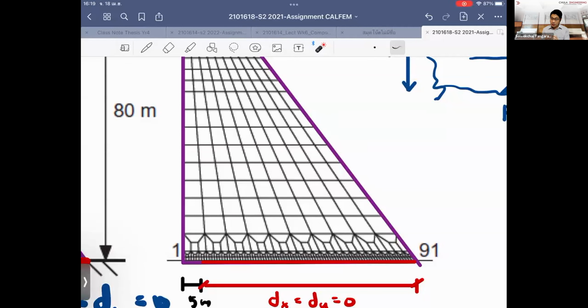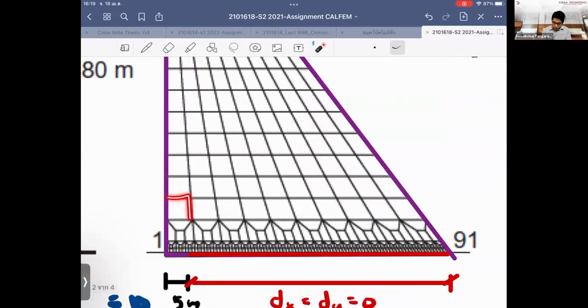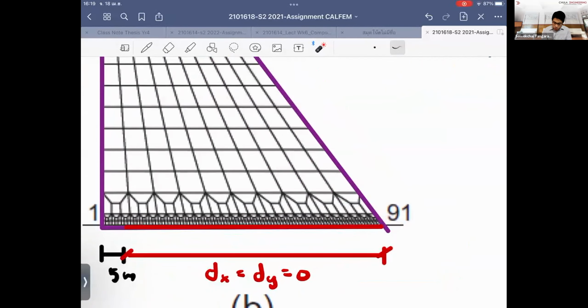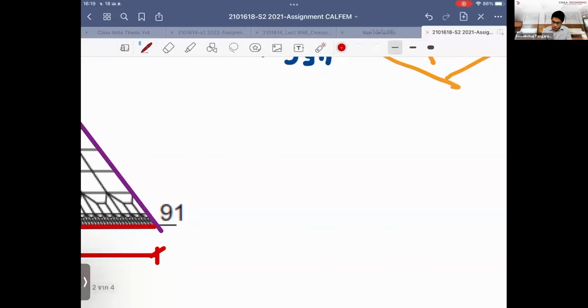The more meshes you have, the more accurate the stress that you can obtain. If you use the uniform one, we call this uniform refinement, right? You would need so many elements in the model, and that is very painful. So what I suggest is that you use some type of transformation. The nice thing about this type of mesh pattern is as follows. Listen to me first.